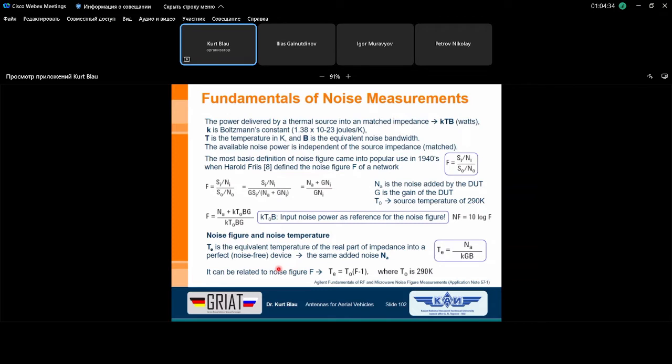Again, starting with the antenna, then connected to a preamplifier, for instance, a mixer to make the input frequency lower, in a so-called intermediate frequency, and then our, let's say, demodulator detector. Okay, this is a normally used receiver block diagram. Sorry that it's not here in one of the slides.